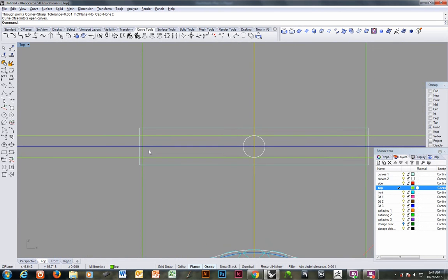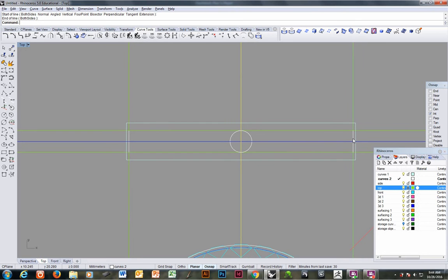And now we're going to draw, revise the drawing of our top view. Int snap. Actually, I'm going to draw a polyline from here to here, here to here. Enter when done. Here, here, here, and here. Enter when done. Going to grab those two polylines by holding down the Shift key and click Select, and then trim.